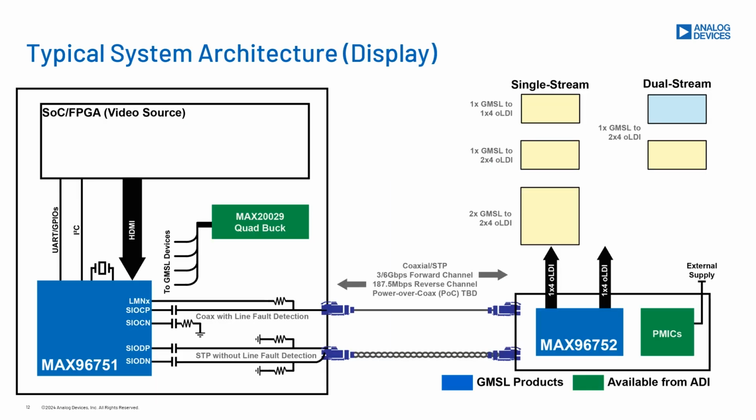Display applications sometimes have higher bandwidth requirements, and you'll see some GMSL display devices with 2 ports, including this GMSL2 pair we released online. These devices are very flexible in their video stream management. Each link can carry an independent video stream or work in a pair to transmit a higher resolution stream. The deserializer is also highly configurable to display the videos from 1 or 2 individual displays.